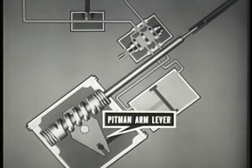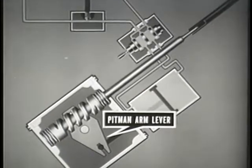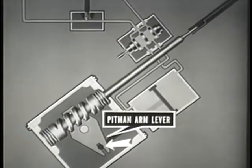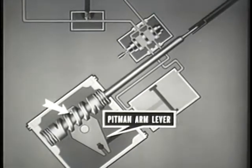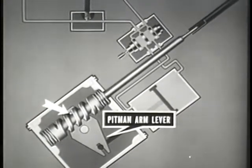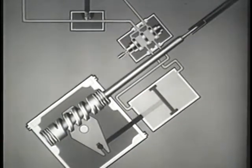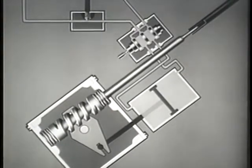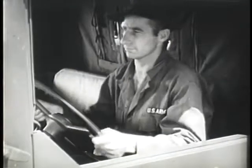The Pitman arm lever, which actuates the Pitman arm, has one end fastened to the piston rod, the other in mesh with a groove in the steering cam. When the steering shaft is turned, it requires a greater effort to turn the Pitman arm shaft and lever than to compress the springs at either end of the cam. This is so because the Pitman arm shaft and lever are connected to the front wheels.